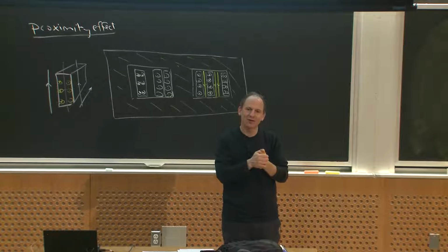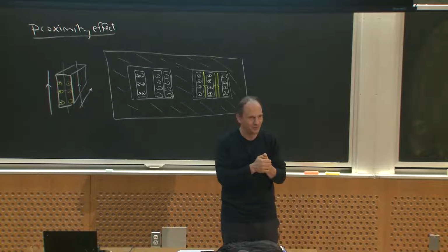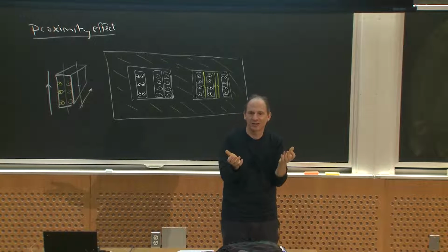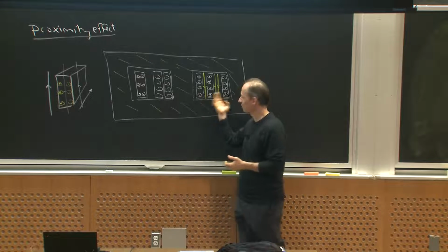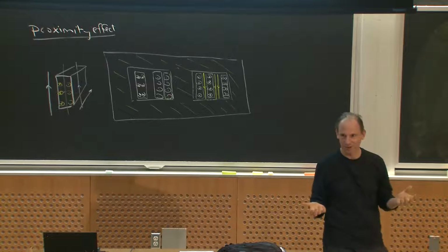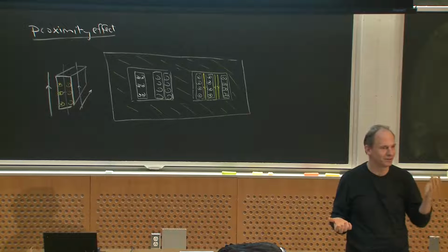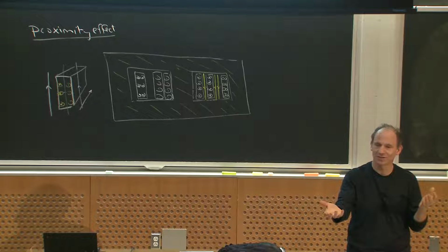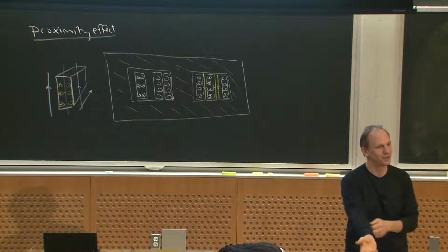And then you could think, oh, but if I include skin effect, it's 20 or 30 milliohms because I have a bunch of skin effect. And then you figure out what the proximity effect is. If you have a bunch of layers, the loss can sort of go as the square of the number of layers, you could have 300 milliohms, right? So whereas your DC resistance might only have been 10 milliohms, suddenly you've got 300 milliohms. That's a factor of 30 times the loss you were expecting, right?